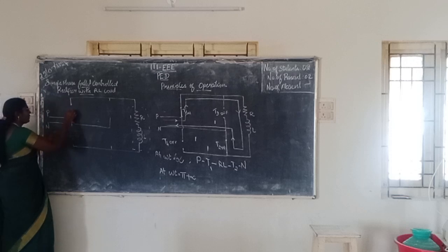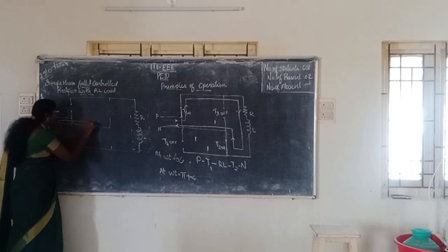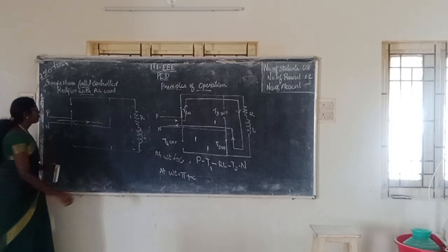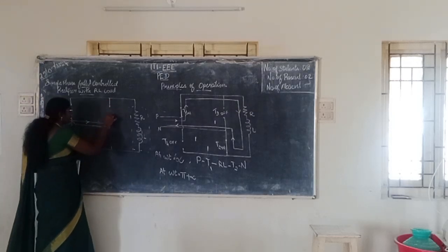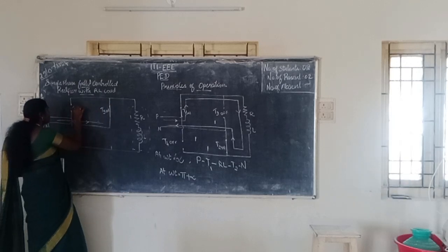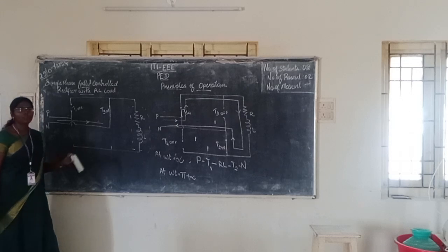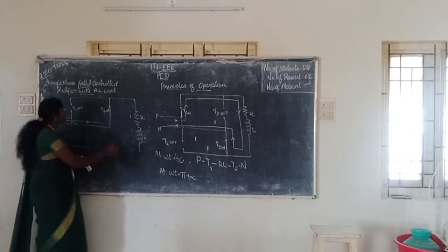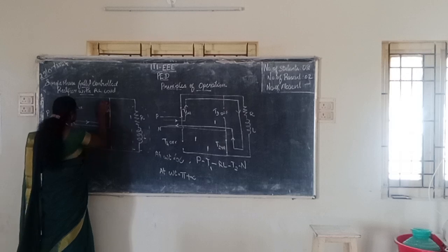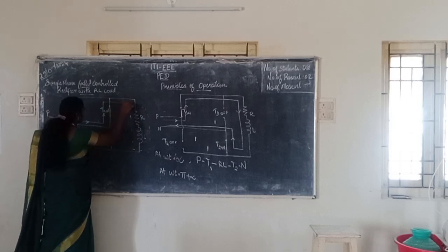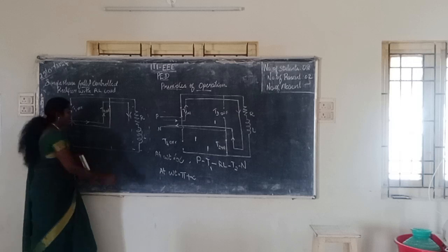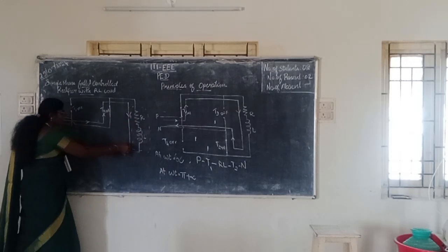What about the switch T1? Off state. During the negative half cycle the current will flow from the neutral. So now, which switch will be in the on state? T3 will be in the on state condition, so I can join that line. I can't join the T1 thyristor since it is in the off state condition. The firing angle pi plus alpha is given to T3. Next, the current will flow through RL, so in this direction it will move. Later it will flow through the RL load.